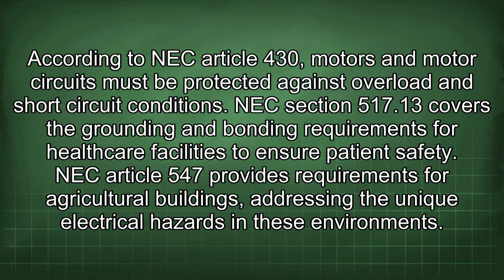According to NEC Article 430, motors and motor circuits must be protected against overload and short-circuit conditions. NEC Section 517.13 covers the grounding and bonding requirements for healthcare facilities to ensure patient safety.